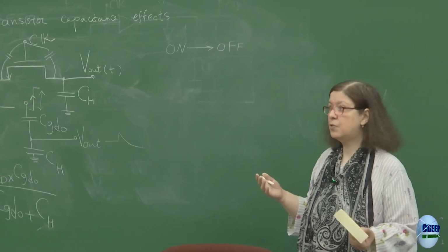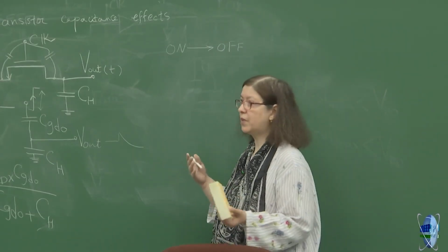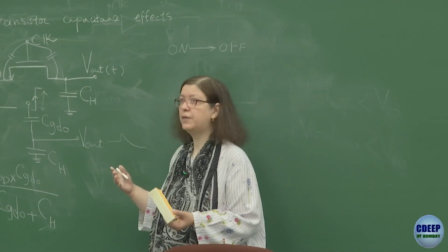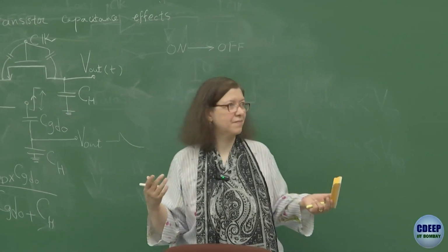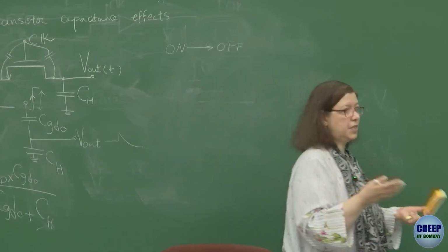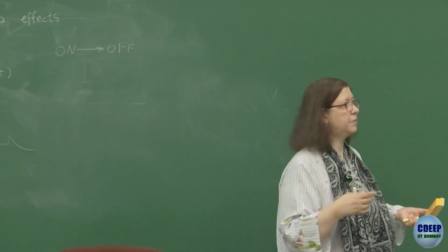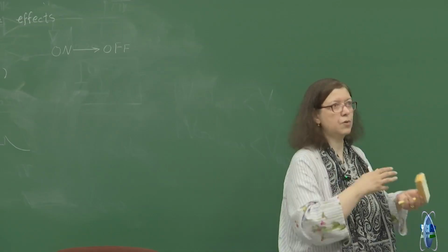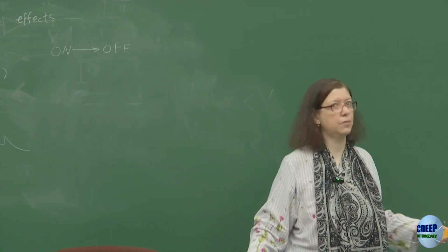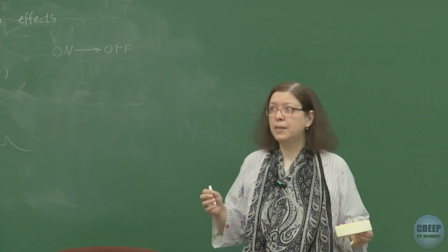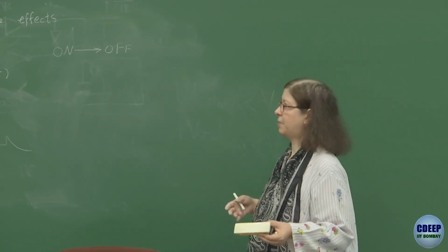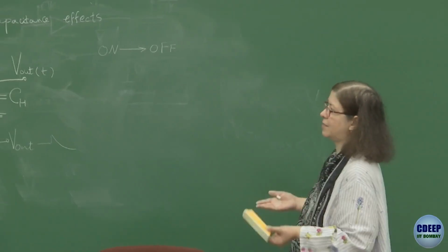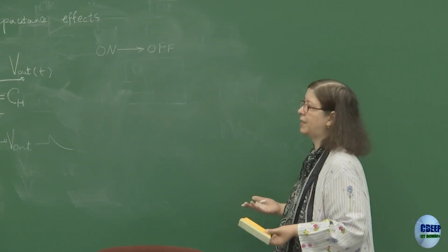When a transistor goes from on to off, the channel will become free of charge, right? Because those electrons which inverted the channel to n-type now have to go back through the source and drain terminals back to the ground. We ignored this effect when we were analyzing the switch without capacitors, but now we have to consider that. It's a capacitor between the gate and channel.